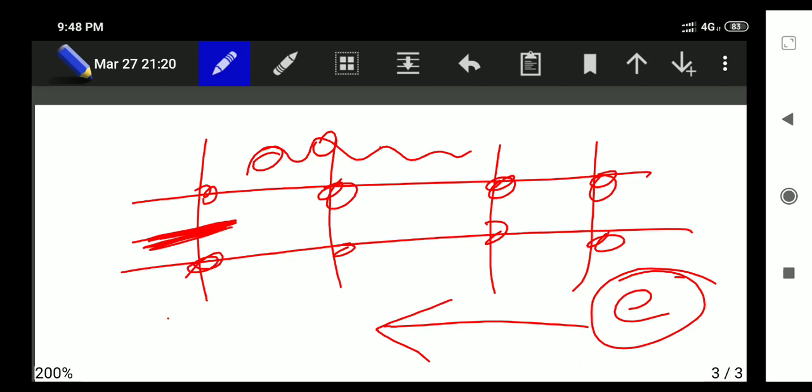At the same time, as you increase the temperature, the vibrational energy of these lattice points will also increase. That means the energy of the phonon will increase, and there will be more phonon generation and more collision with the electrons. So the collision between electron and lattice is one of the reasons because of which we have resistivity in a system.